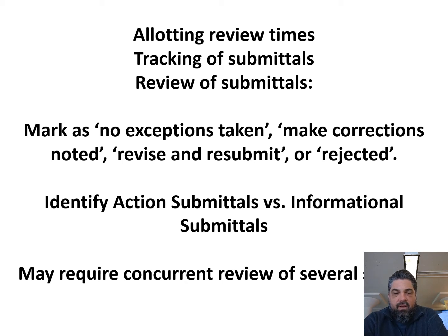And note that you may require the contractor to submit several submittals concurrently, because you'll want to review them at the same time. And so that means you're trying to look at 2 or 3 different systems, and you'll ask for those to be submitted concurrently, so that you can look at all those submittals together, rather than piecemealing it weeks and weeks apart.